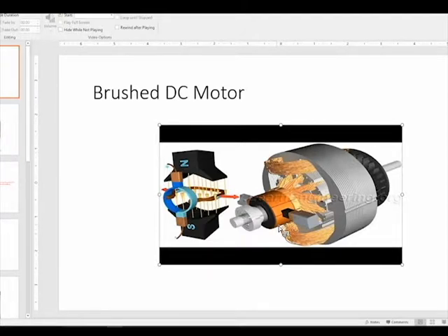Okay, so these brushes are in decent shape. These ones are all torn to shreds. You can take a look at this. Oftentimes the motors fail because the brushes wear out, so you can see an example of brushes that are really torn apart on this one from overuse of the motor. So I'll pass both these around. This is a magnetic coil which creates the flux in the stator. This has a permanent magnet which causes the flux. That's these heavy pieces here on the outside. That's a permanent magnet.